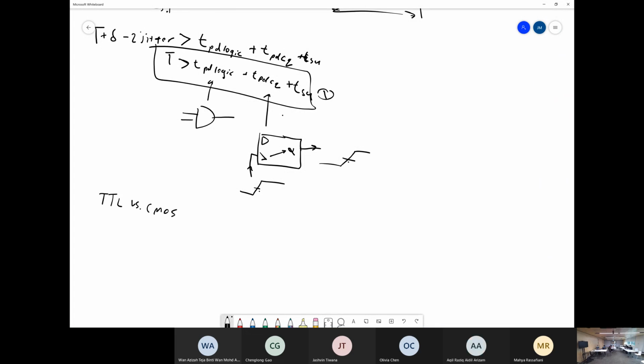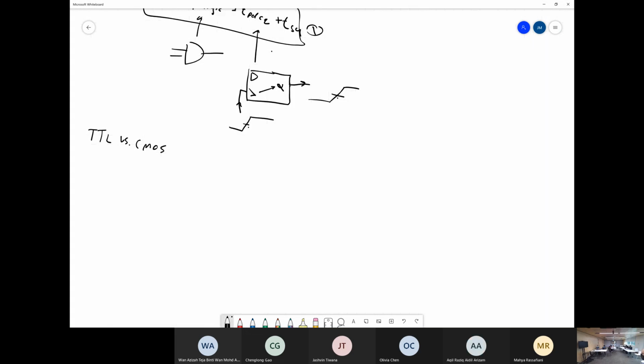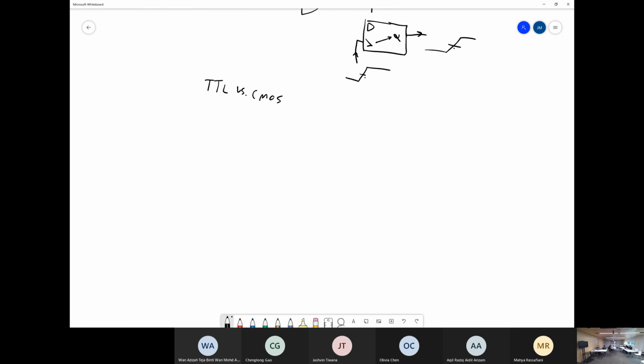So it's good to know the differences. They're all transistor based. TTL is BJT based, usually with different doping concentrations. You can have Schottky based transistors, or overdoped Zeners, but the point is that you'll have some sort of NPN or PNP transistor in there. CMOS are MOSFET based.